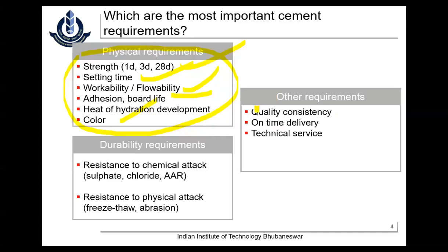This problem I used to face when I was working in the industry, from the cement division people actually. I really had a tough time whenever there was a change in the quality. Sometimes we don't know how much fly ash or slag, especially with fly ash cement, the cement division people never reveal how much the blending is. The test certificate says something, but truly speaking, that is not the case. There's also a lot of variation: sometimes it is 20%, sometimes 28%, sometimes 30%, 32%. Because of that, I cannot change my mix designs very often. This problem I used to face a huge number of times.